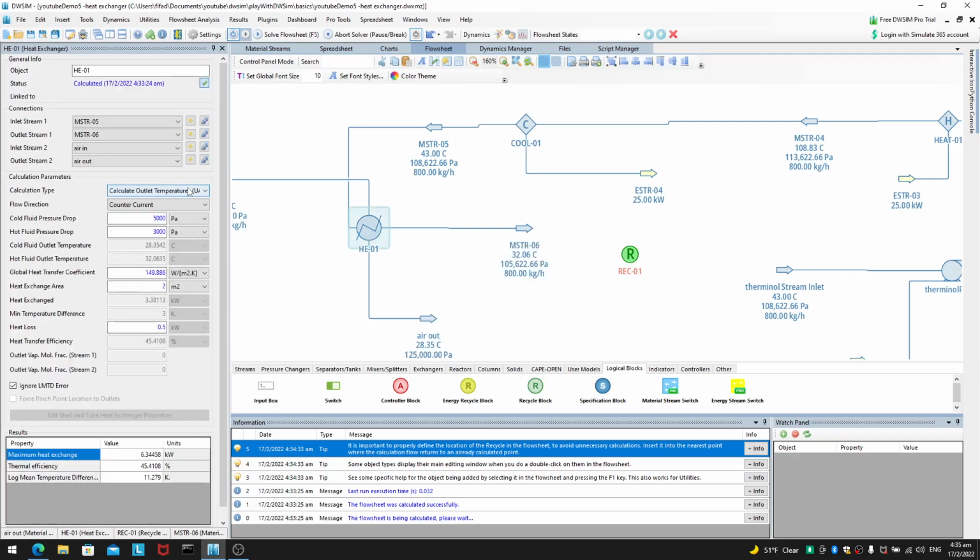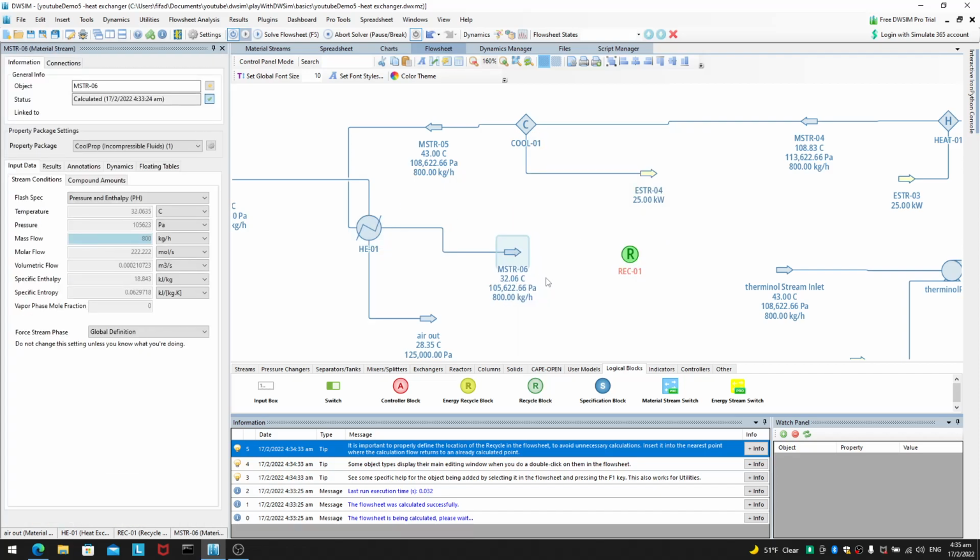For that, I strongly suggest you use this shell and tube exchanger rating or fouling factor method. Go and play around with them, and you will see that your pressure drops for hot and cold fluid are calculated in a more realistic manner. So that you can play around with them eventually.